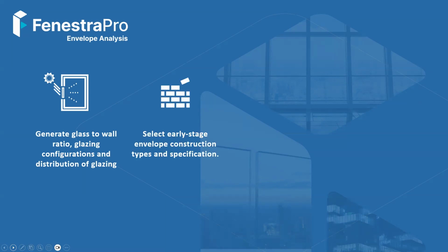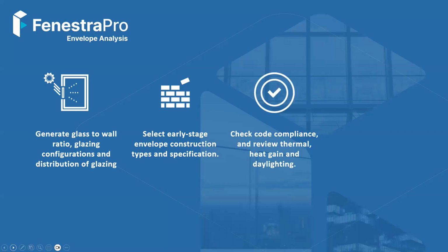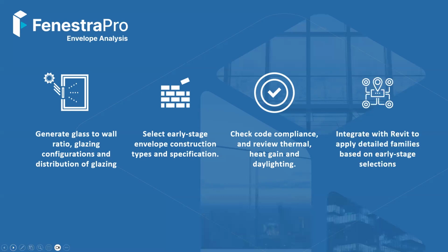We're able to select early stage envelope construction types based on a number of parameters and apply those to our Forma model. We can check code compliance in any particular region that you're in, a particular country or state, for example. We can identify what codes are relevant, and we can start reviewing thermal heat gain and daylighting performance and see how that relates to your code compliance.